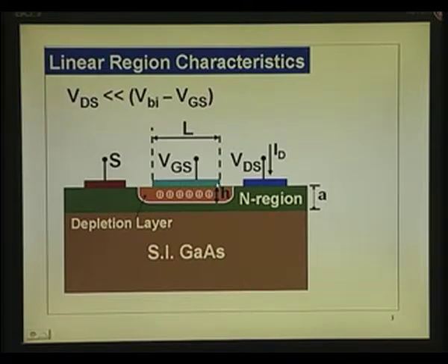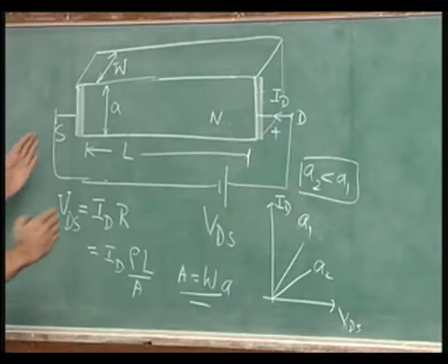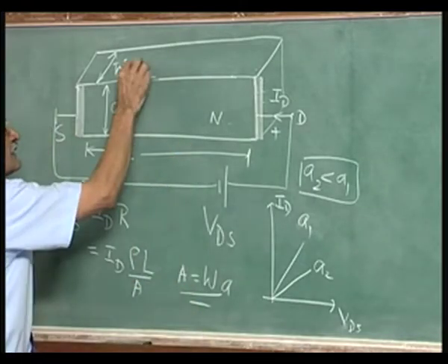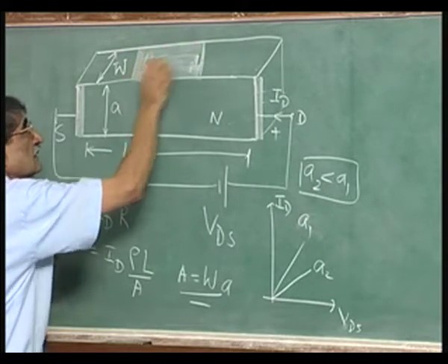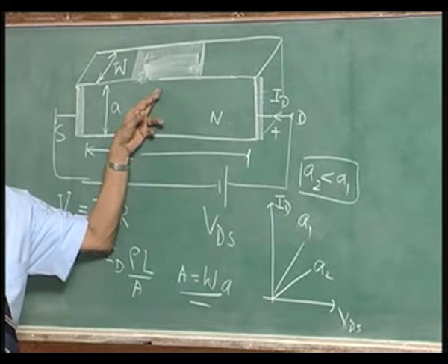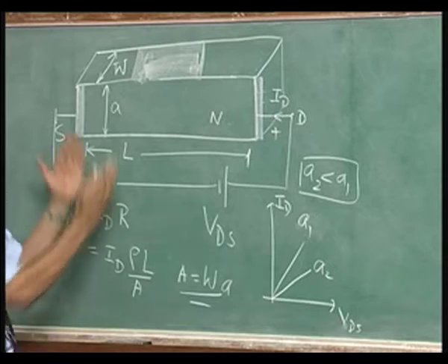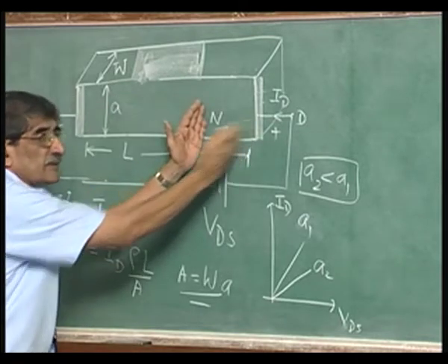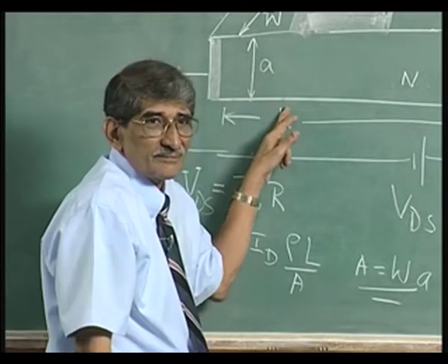We are telling that you do not put physically the contact there, you put it slightly away from that, because you do not want to short this gate to this source region. So, there must be a separation between the two regions. So, what you will have is a contact put here like this. That is a contact on the top that you have put. In our first analysis, we will neglect the drop across that. What is the meaning of that? It is as if the contact is put here.